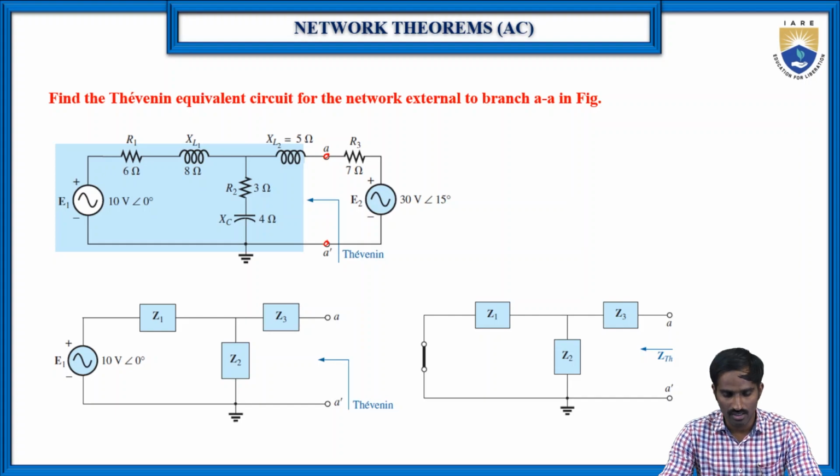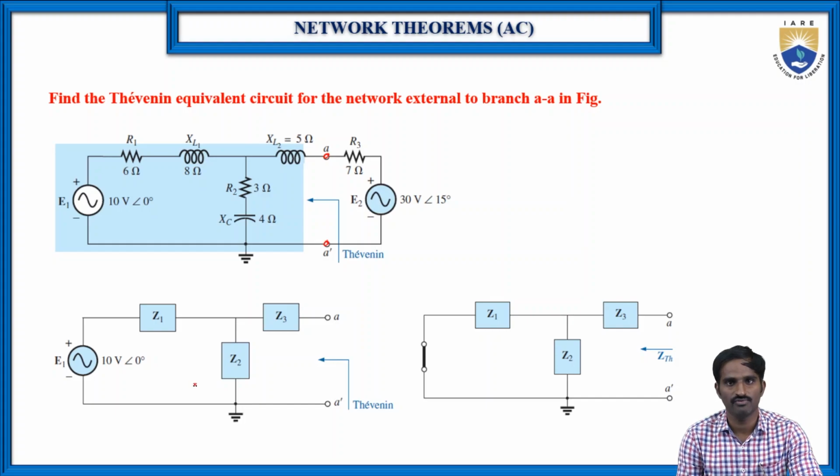So here I have just drawn which circuit we should use to find the Thevenin's voltage, and also which circuit we should use to find the Thevenin's impedance or Thevenin's resistance. By using the first circuit, we can find the Thevenin's voltage, or the open circuit voltage across the terminals A and A dash.